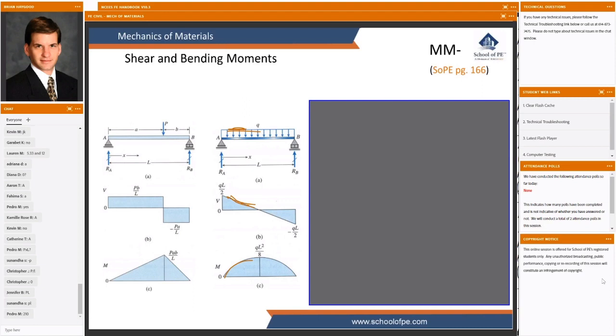And we know due to symmetry that we'll have a point of interest where the shear diagram crosses 0 in the middle. So we'll have a local minimum at 0 and L, and we'll have a local maximum at L divided by 2. And the area of this triangle is the magnitude QL squared over 8 that they've used for the top of that diagram. So that one's very similar to what we already worked.